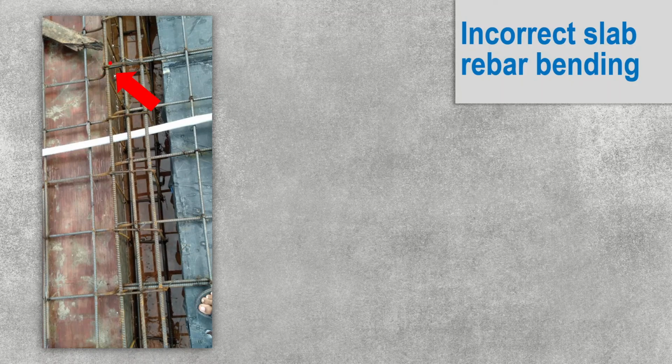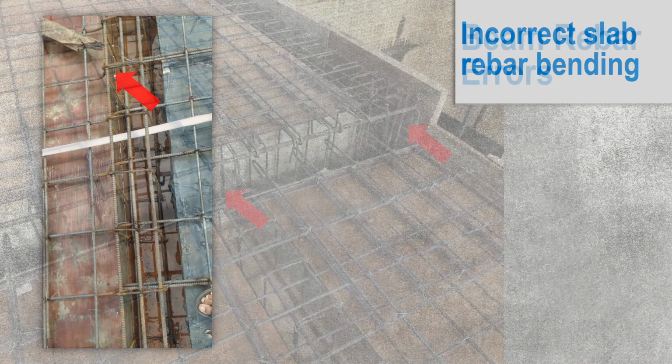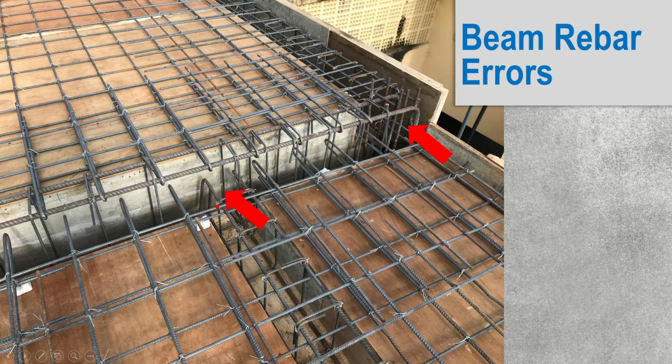So therefore we have to be very careful. It could straighten like this, and it won't carry the tensile stress. So there could be an issue in the structure. Therefore we have to be very careful, and we have to follow the structural drawings correctly during construction. Or else, if you don't have a structural drawing, it is advisable to get advice from a suitable person before the construction. In this figure there are two errors.